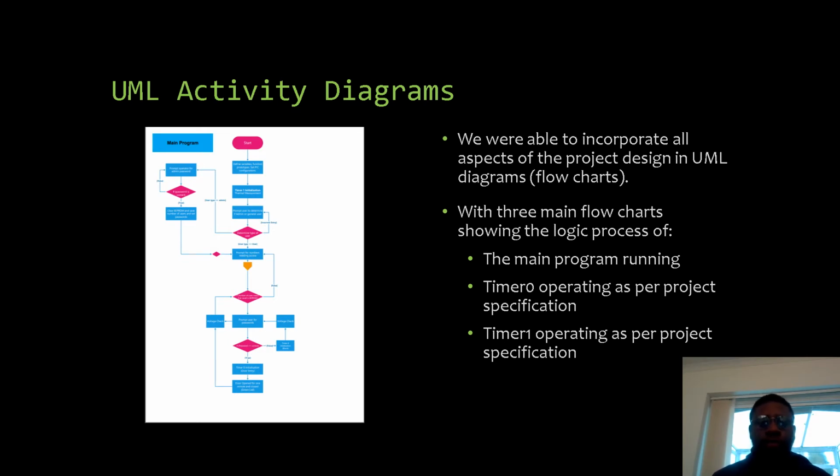Timer 1 worked as a 5-second interrupt, which worked as a measurement aspect. So every 5 seconds a measurement would be taken, and this was for the temperature calculations that needed to be done before the 7th segment and the averages were calculated. And these two flowcharts as well can be seen in our final lab report, which shows the different flags and different registers that were used for timer 0 and timer 1 and the sequence of events.